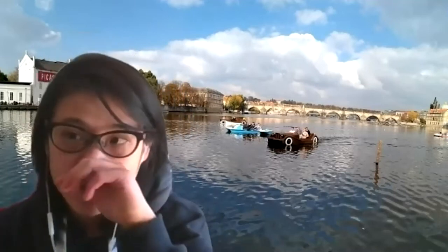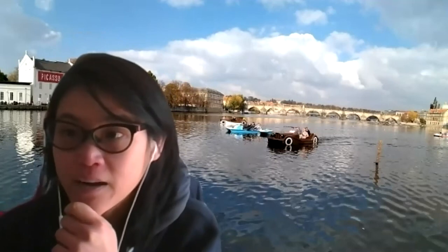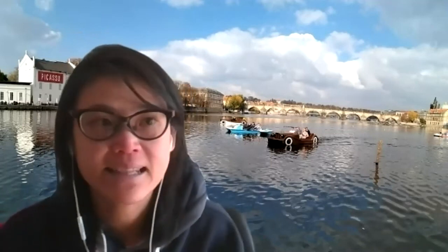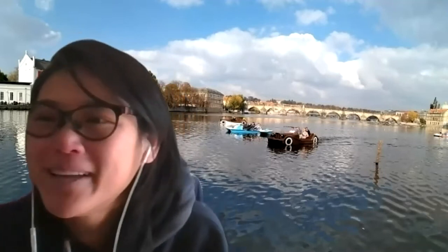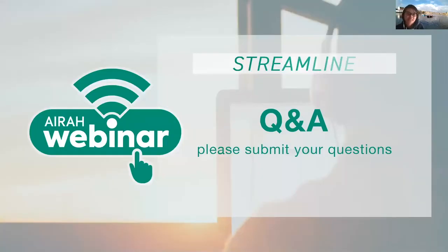So the first one is John's question. How do you get to 5,000 hours per annum? Is it an accumulation of the number of pumps running? Yeah, it's basically how long the system operates for. So if you had, let's use my lead lag standby configuration. Obviously, the lag pump may operate fewer hours than my lead pump. But I'll be looking at the whole system and saying, actually, my whole system operates 8,760 hours per annum. So we're looking at a system perspective.